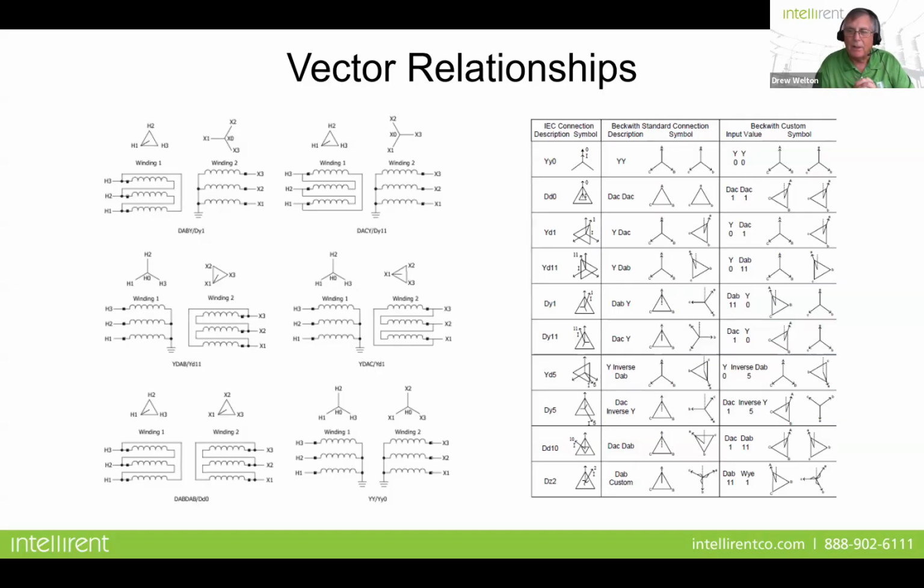One of the reasons is that if you don't have this configured correctly in the relay itself, or you don't test it accordingly, you either won't get a good test of the relay when you're commissioning it, or the relay is going to nuisance trip when it comes online, because if you don't have those phase angles compensated correctly, you're obviously going to get a nuisance trip.